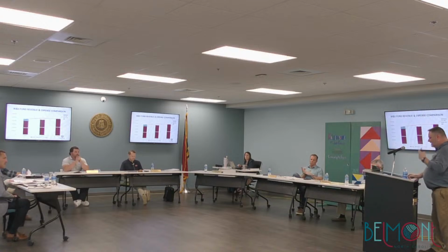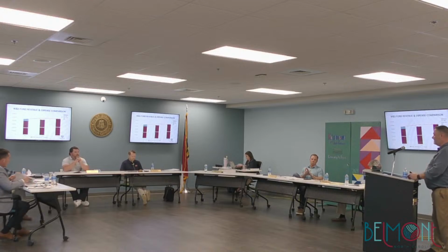So really, we need to bring in more money so we can do I&I every year. You ask, do you do I&I? No, it's something that you should. You're always gonna be chasing it, but you should always dedicate money to do some I&I and do that smoke testing, and other things that go along with it. We need to be doing line replacements every year, a little bit, and we have those plans.